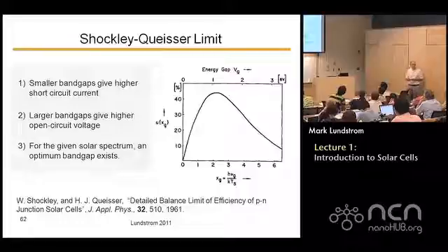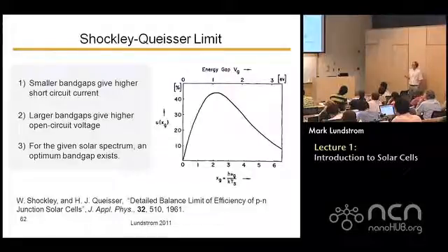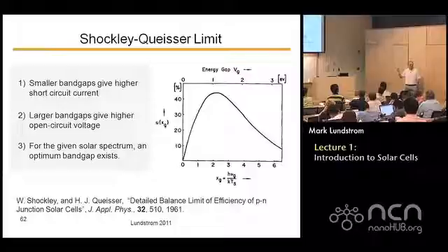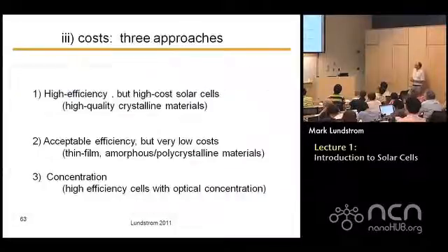Gallium arsenide is also very close to the optimum. So if you're going to pick one band gap, you'd pick something around just a little above 1 volt, to give you the best efficiency. And you can see the numbers here. The best that you could possibly get is a little over 40%. I think people have refined these calculations, and the optimum is felt to be a little bit lower than that now. But it's up around 40%.